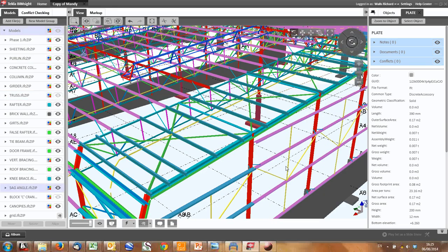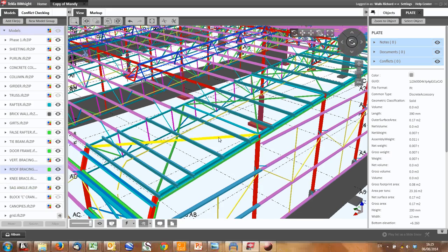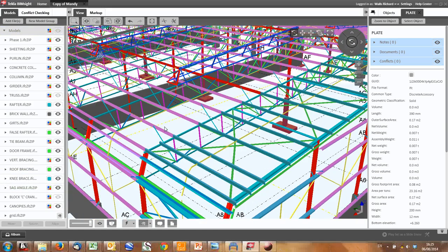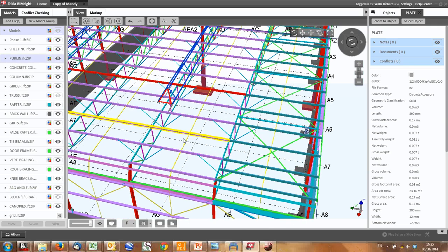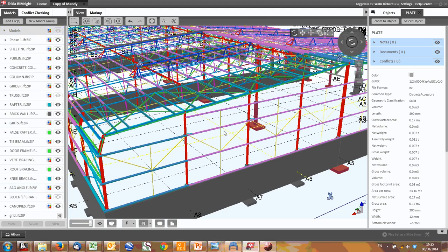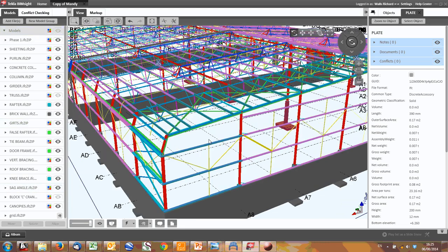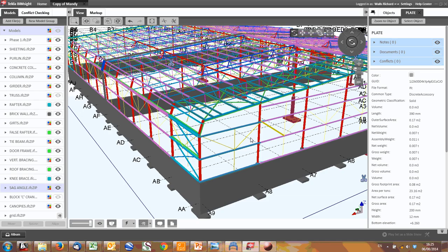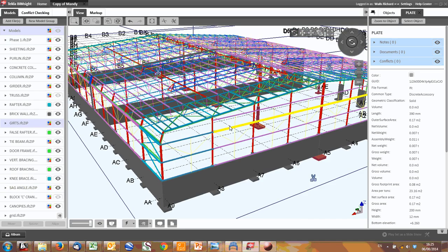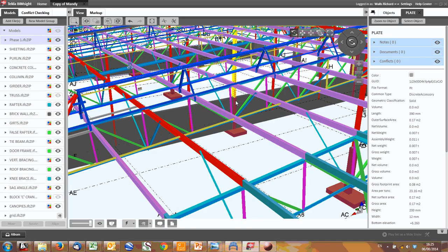The sag angles, those are the sag angles in the other there. They support the girts and purlins. They prevent them from twisting and warping, and also prevent them from sagging while they're installing them. If you don't have the sheeting on it, these sag a lot downwards, so they prevent all that sagging. Then we've got our columns here, columns all the way around. This is the gable face, so these are gable columns. Got some internal columns there.